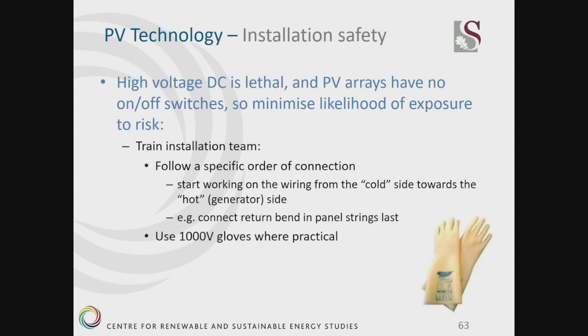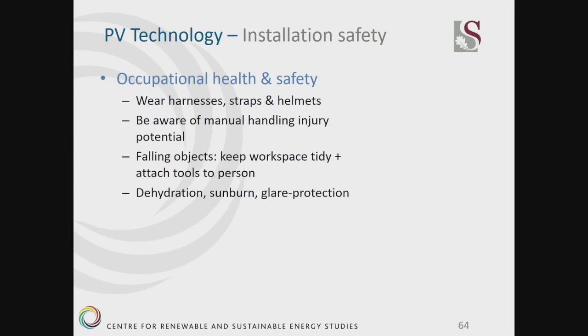Use 1000-volt gloves where practical. It's not always easy to work with these gloves. They are thick rubber gloves, so you can't do fine motor things with your hands, and you might want to take them off, but you need to take care of that situation. No bare feet or shorts should be worn, and when you do an installation, a first aid kit should be close by. So there is the Occupational Health and Safety Act, and this is there for your safety.